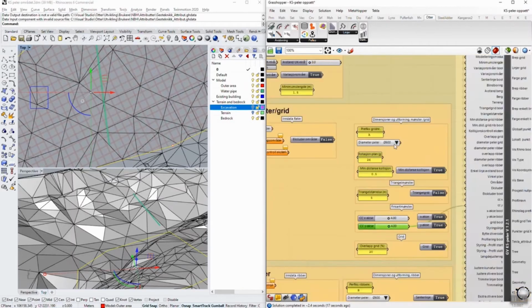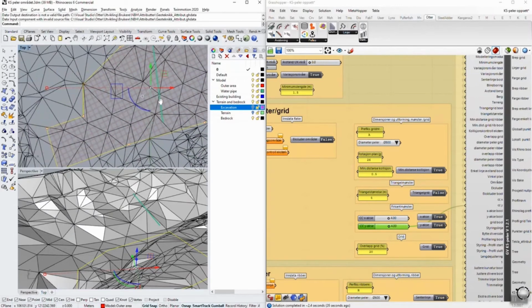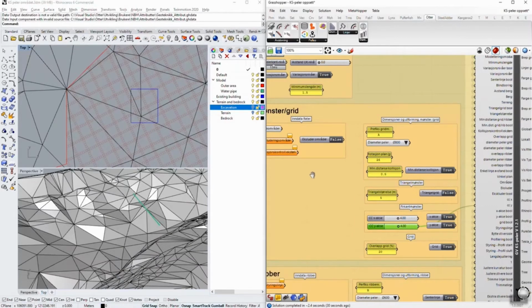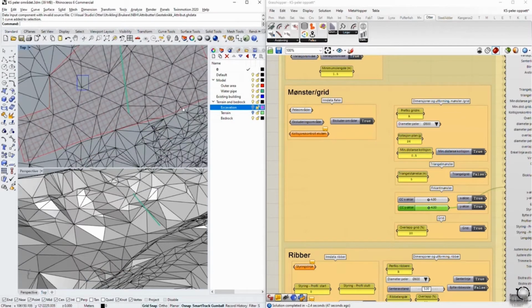And we can just as well finally choose the desired or the calculated dimension of the lime cement columns. Okay, but what about the building? Then we just choose, like we used to, our exclusion area in the script. And voila. Okay, might take some seconds here, and this is by the way in real time. So now all the columns in that area are removed.